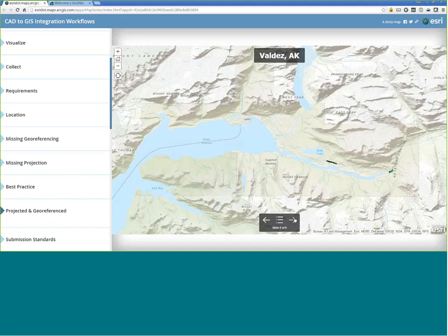Then I had the same issue come up with Colorado. I did the same exact thing. I think they're State Plane North and South, so I created a State Plane North and a State Plane South folder, took a couple of the CAD files they shared with me, stuck them in that folder, and renamed the PRJs for Colorado State Plane North and Colorado State Plane South to Esri_CAD and stuck them in the respective folders. When I loaded those CAD files into ArcMap, they just dropped right into place, exactly where they needed to go.